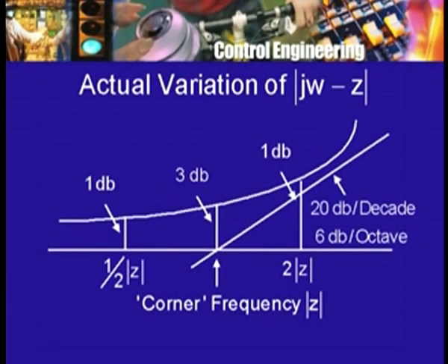Now, this was for one zero. Now, the transfer function may have several zeros. So, then what happens? As we saw, the reason for taking logarithm of the modulus was because the modulus was the modulus of a product of numerator terms divided by a product of denominator terms. Taking logarithm converts the product into sum, converts the division into difference. So, essentially what we have is, if we have 1 zero, then we have this approximation. The 1 zero will correspond to one corner frequency. If I have another zero, I will have another approximation with a different corner frequency, and so on.